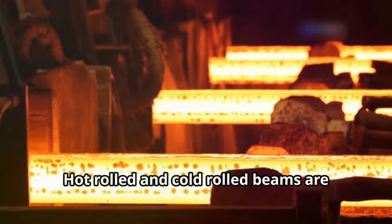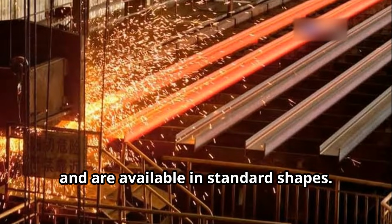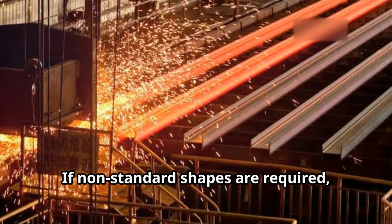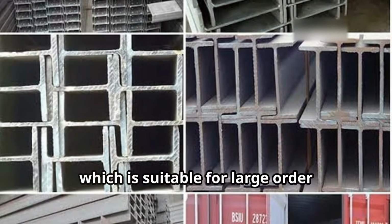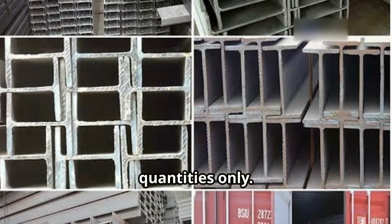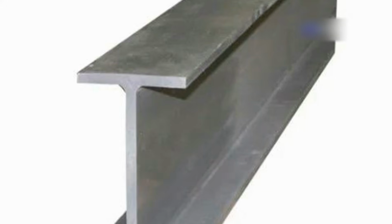Hot-rolled and cold-rolled beams are constructed from one whole piece of metal and are available in standard shapes. If non-standard shapes are required, the entire manufacturing setup has to be modified, which is suitable for large order quantities only. Aluminum I-beams are manufactured by extrusion.